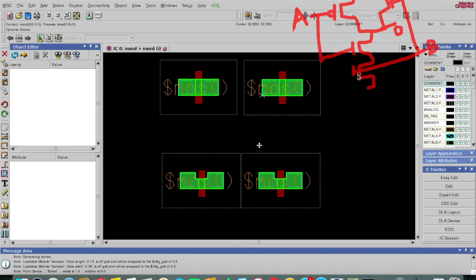So we are going to connect these in this manner. One of the terminals of NMOS is ground, that is source. Source is grounded. Then drain is connected to the source of the other NMOS, and the drain of the other MOS is connected to PMOS, and output is taken from that point. So first we'll focus on this. And the other thing is the gates are connected. The gate of PMOS and NMOS is connected. So for input A, we can connect these two, and for B, we can connect these two gates.